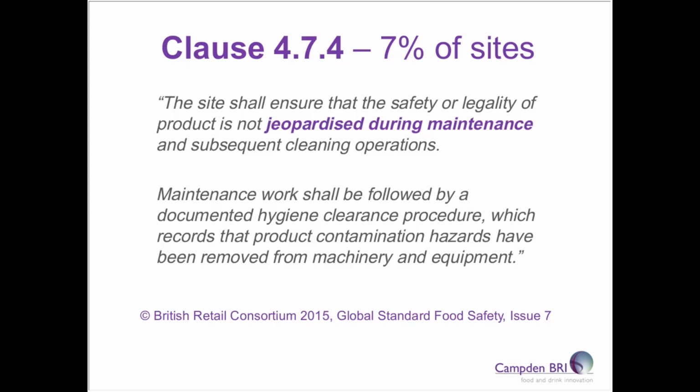Next clause, 4.7.4, 7% of sites have this as a non-conformity. The site shall ensure that the safety or legality of product is not jeopardised during maintenance operations and also subsequent cleaning tasks. Maintenance work should be followed by a documented hygiene clearance procedure which records that product contamination hazards have been removed from machinery and equipment, so a handback to operational activities.